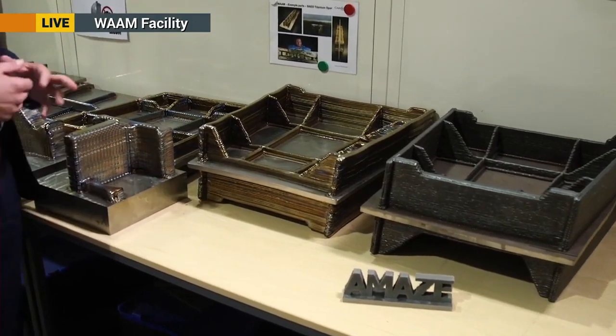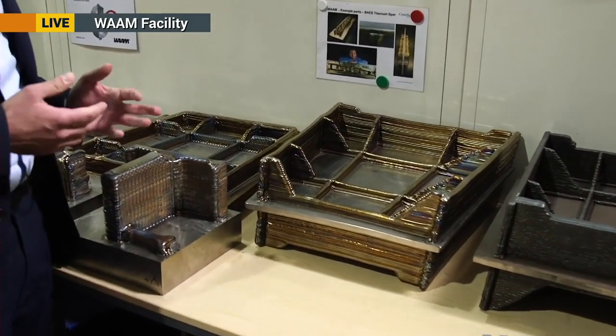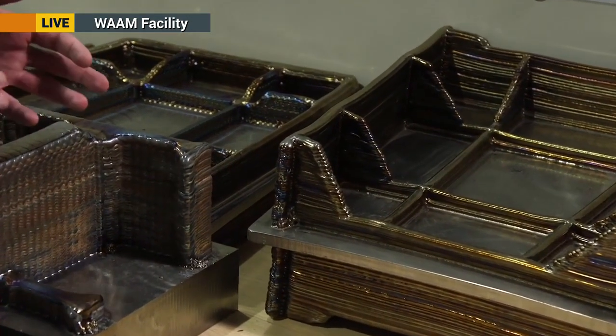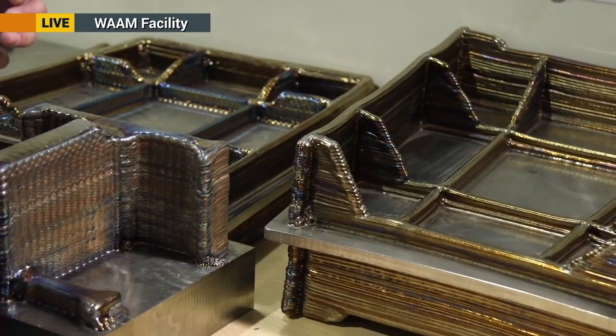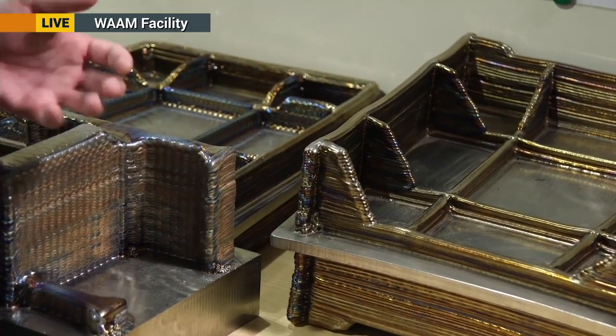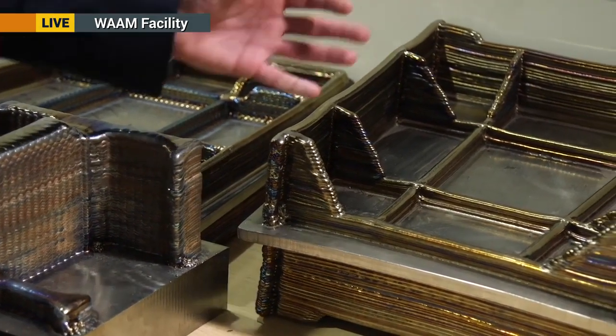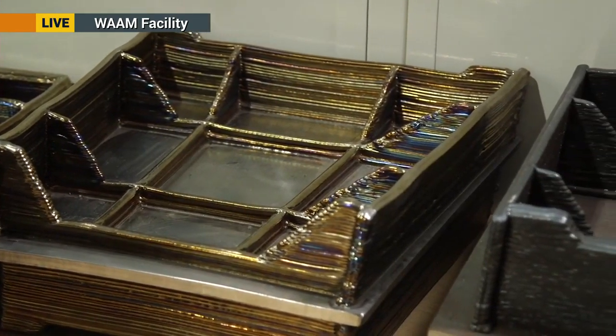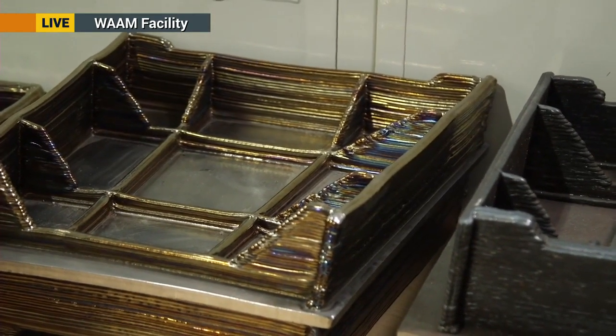For example, this outboard landing gear rib that we made more or less 8 years ago for Bombardier. Traditionally, this part would be machined out of solid or of very rough forgings. You would start from a billet of over 250 kilograms in mass. You would spend quite a lot of time machining it away, removing this fantastic titanium in the form of swarf until you are left with the final geometry. And of course, that swarf can be recycled, but just to give you an idea, we might buy billets for 60 pounds per kilogram, and we sell that scrap for 60 pence per kilogram. So there is quite a lot of waste in money associated with that.